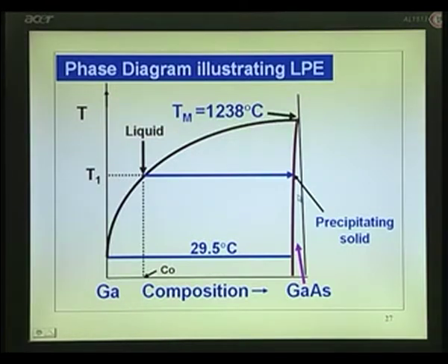This is the benefit. The major benefit of growing gallium arsenide from a melt, this is called solution growth. From a solution, you get gallium arsenide at much lower temperature than melting point. What could be the benefit of this? Okay, now when you do that, slightly when you come down, you get that composition, it loses that gallium. So, the gallium concentration comes down. So, when you slightly come down along this curve, what happens is, when you freeze, I am just showing it slightly below, but for clarity I will show it a bit below.